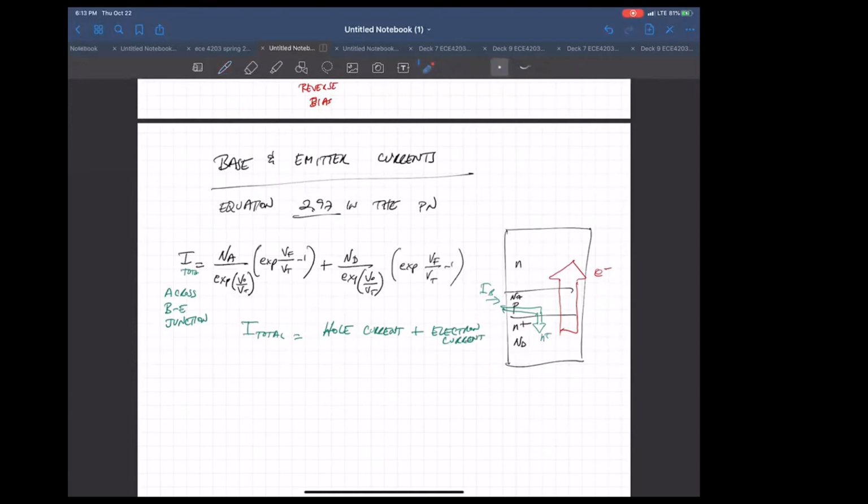And this is the equation for that. So if I look at this, the total current is proportional to N sub A, and the electron current is proportional to N sub D. We've talked about this, we're beating it to death, but it's very important that by making the doping concentration of the emitter, this N sub D, much, much higher than the doping concentration of the base, the electron current is much, much higher by this ratio of ND to NA.